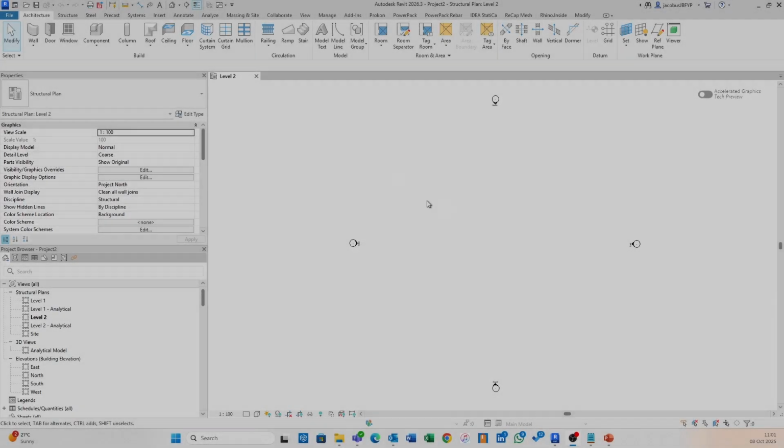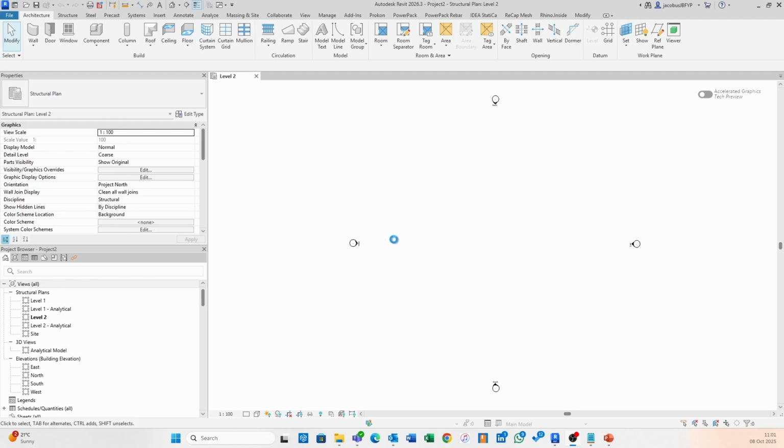All right, so in Revit, one of the first things that we're going to do is draw out a grid line, and then we would like to make use of a model line to define the center of that array itself. So first thing to note, when you open up your template, just make sure that you are in the right view. I'd like to go to the level 1 view from where we will start our modeling process.